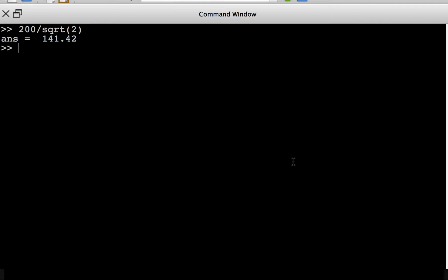So here I will write V equal to 141.42 multiplied by exp. So this is the syntax that we use in MATLAB, exp, and then 30 is angle in degrees, but typically this function we have to give the angle in radians. So how do you convert degrees into radians? So divide by 180 degrees and multiplied by pi. Then this will convert the entire 30 degrees into radians, and then also multiply by I.